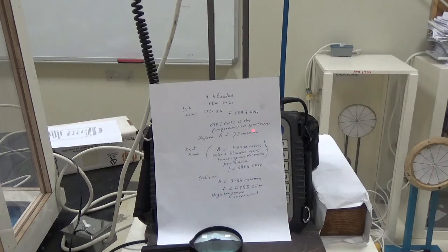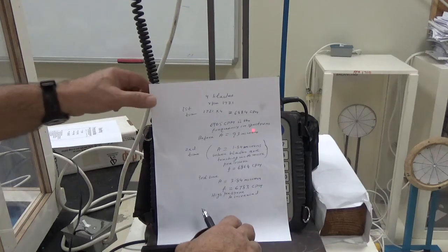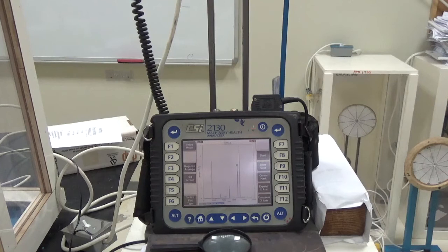And to know the problem, as I have told you, you should know what is inside the machine, what is the geometry of the machine, if there is a bearing inside, a gear inside, or a belt inside, and what frequencies these parts will generate. These frequencies you have to calculate, and for calculating you should know the RPM of the machine and the geometry of the parts. So once you know the fault frequency of these parts, then you will take the vibration reading with the vibration analyzer, and you will see the spectrum.